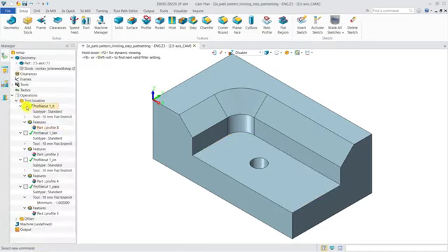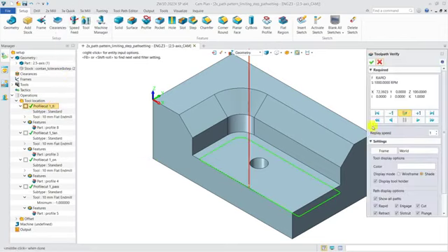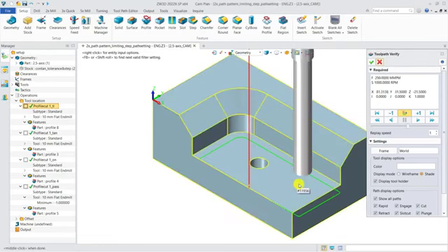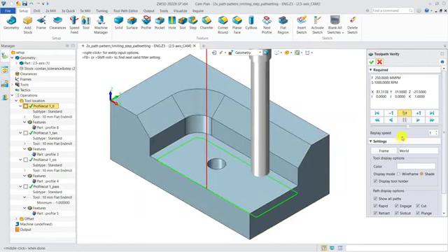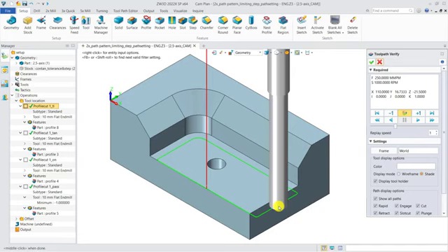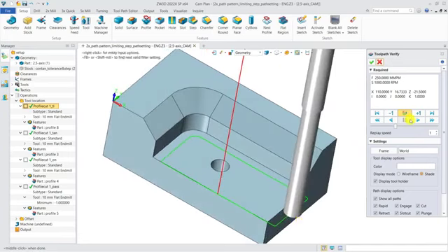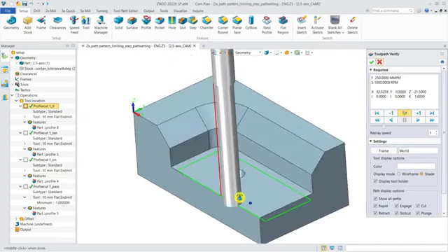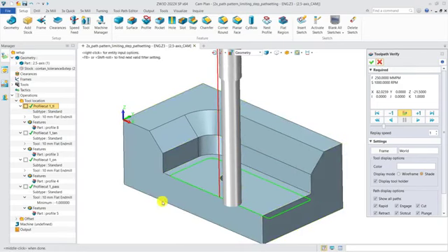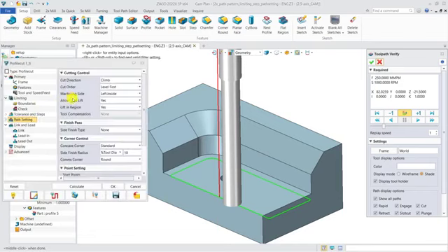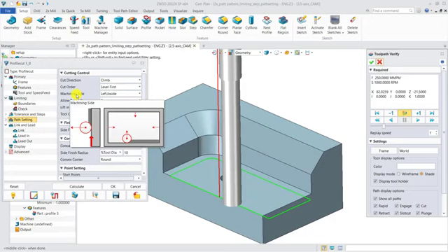Then we can double click to show the tool path and use verify to check the effect. Now it is tangent to boundary and this one is path boundary and this side is on boundary. You may want to know where to specify the inside or outside of the profile. It is right here, the machining side. You can specify the inside or outside of the profile.